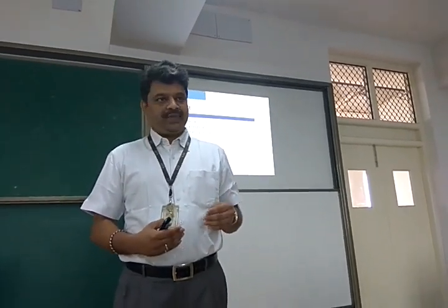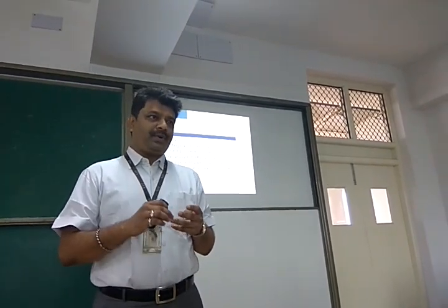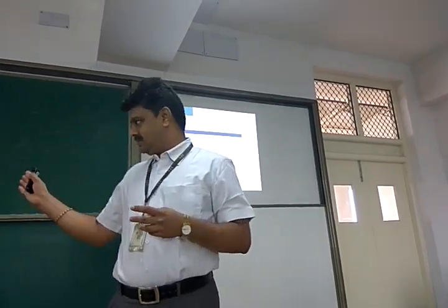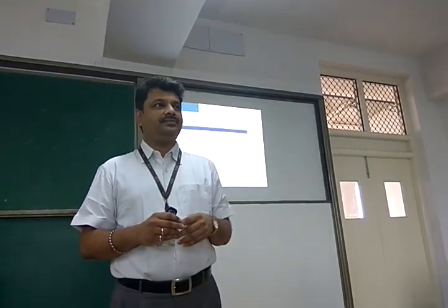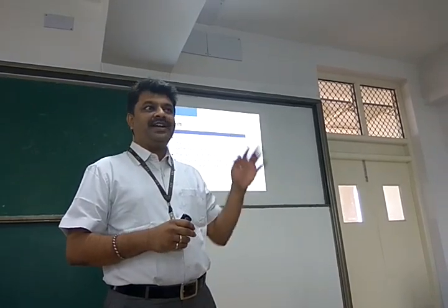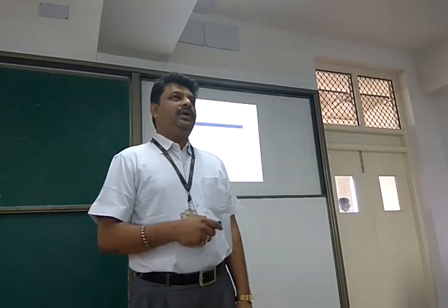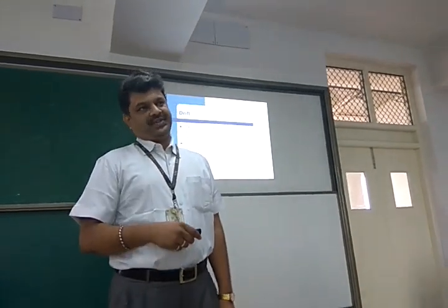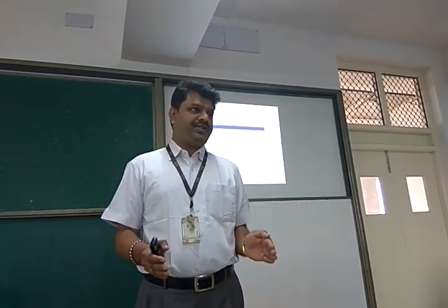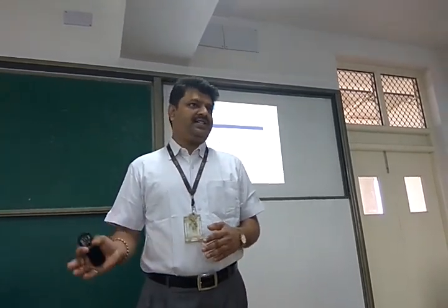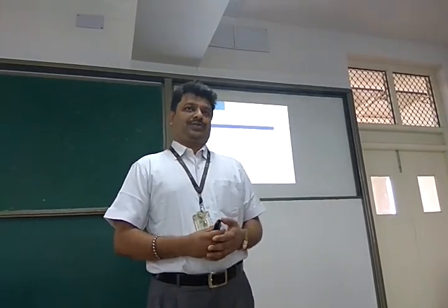Along with precision, there are 4 terms connected to it: repeatability, reproducibility, consistency, and what is the other term? Stability. Yeah, stability. So those 4 terms we have discussed. Repeatability and reproducibility are for short-term duration; consistency and stability are associated with long-term.